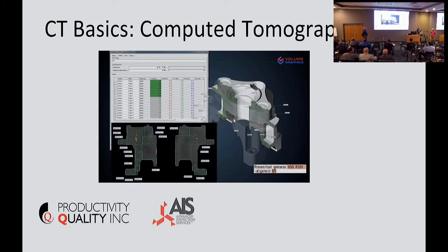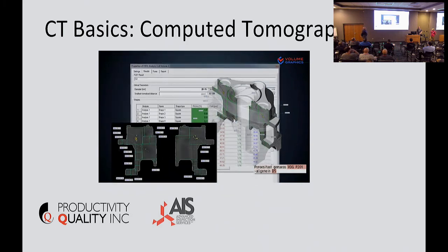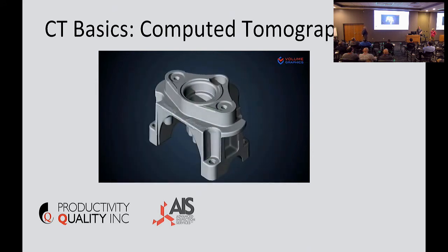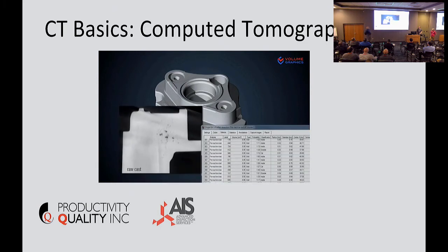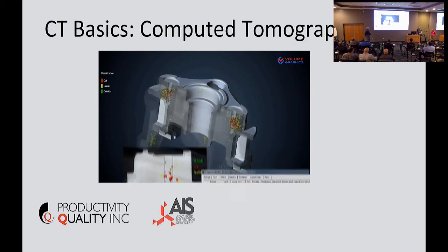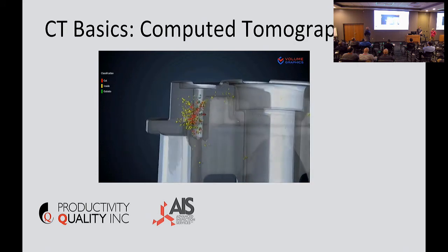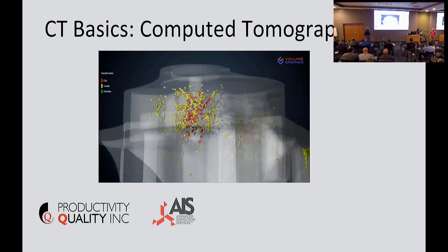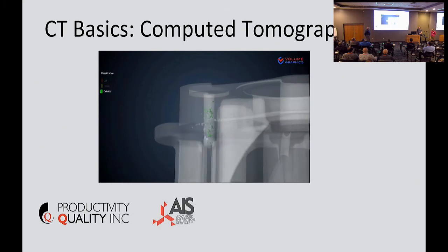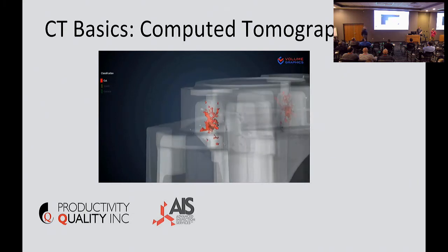But it gives us a way to slice and dice in 2D and 3D fashion and look for different kinds of defects: voids, porosity, inclusions, things like that. And a really nice way to visualize things, and the ability to spin it all around, look at it in great detail, and do an analysis, spit this out all in individual images, but also real data.